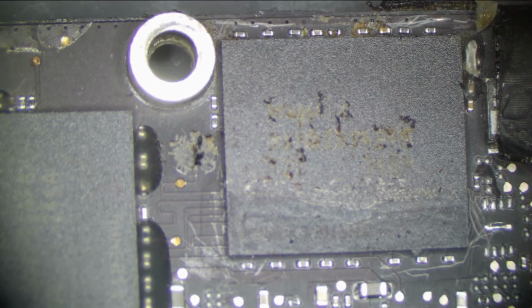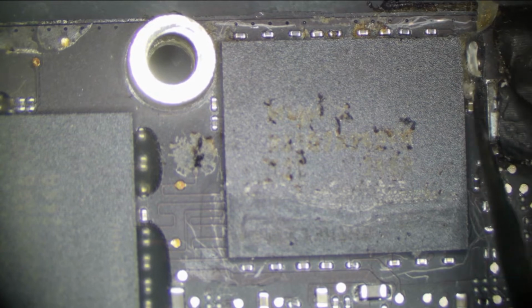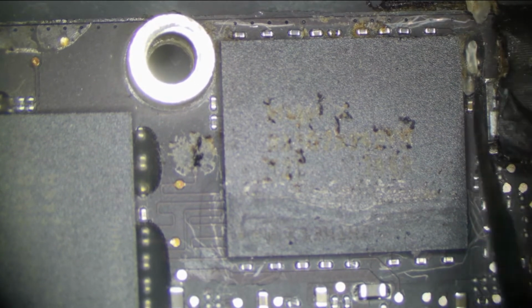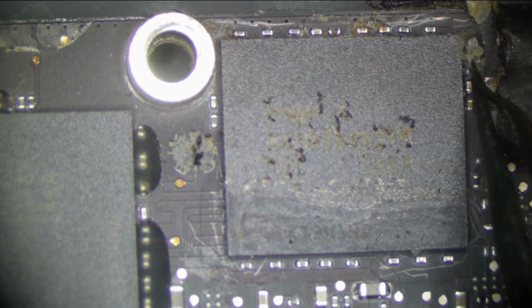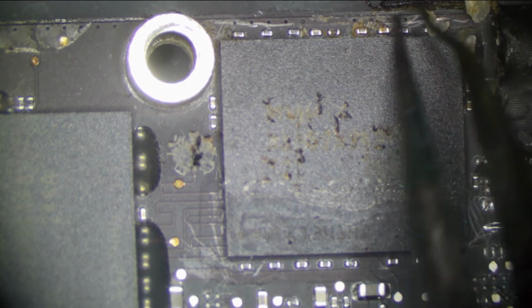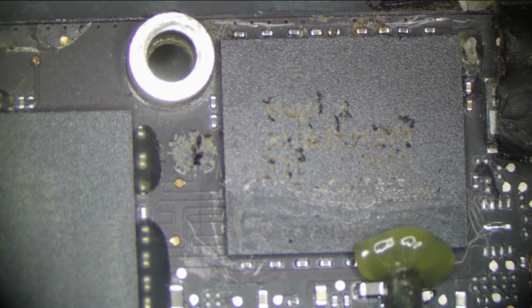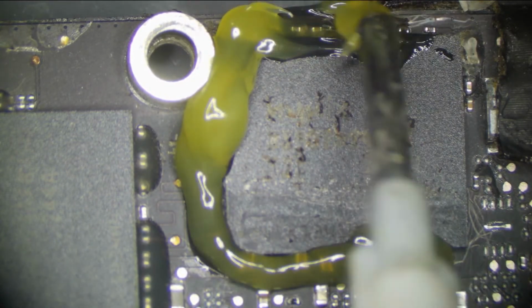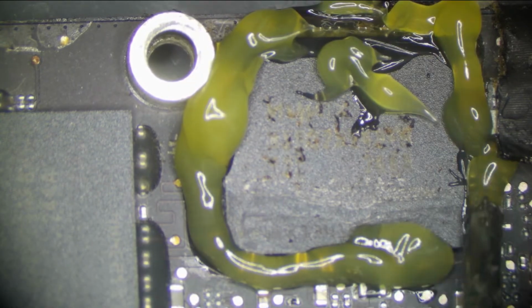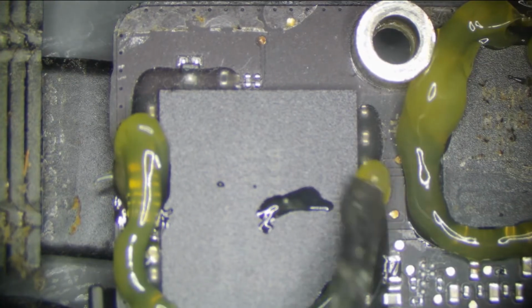A lot of times this edge bonding, especially if it's old and has been hot for a long time, so if it's been under load from the heat from the GPU, it's going to be a real pain to take off, as you can see. I don't want to break anything under it either, so we're just going to roll with that. We're not going to heat this up enough to cause the solder to melt under it. We're just going to heat it up enough to get that flux under there and to wash away all the junk that's under it. I'm going to put some around here too,